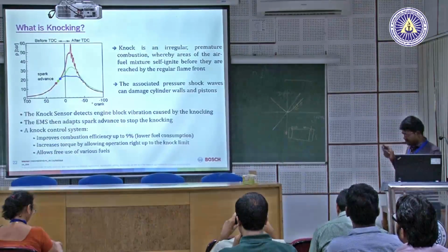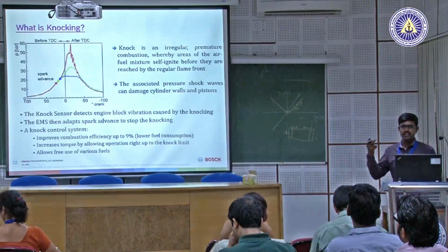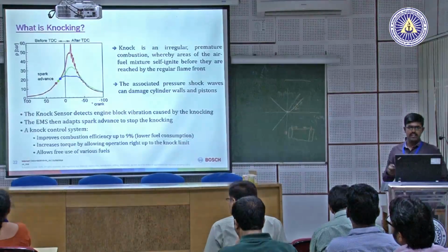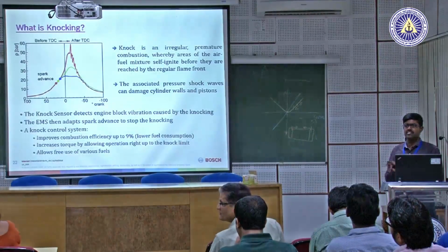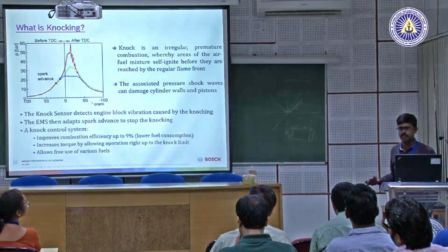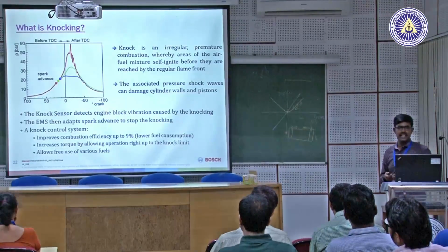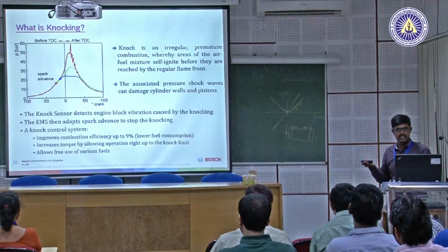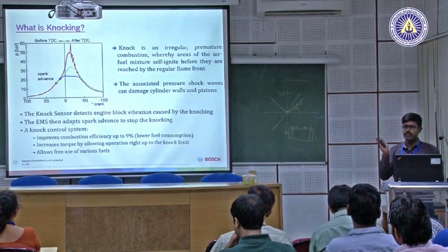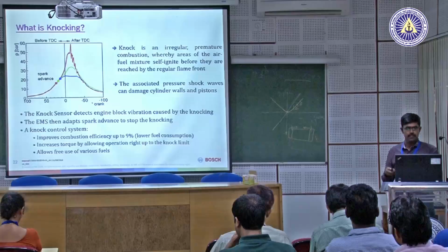So, what is knocking? It is an irregular or premature combustion. It happens when there is a timing delay or advance in the timing for the injection of the fuel. There is a phenomenon where this irregular mixture of air and fuel happens, and there will be some small vibrations caused in the combustion chamber. If the vibrations are very heavy, they can damage the cylinder valves or the pistons. So, you have to control the vibrations by advancing or delaying your fuel injection based on the efficiency of the combustion.